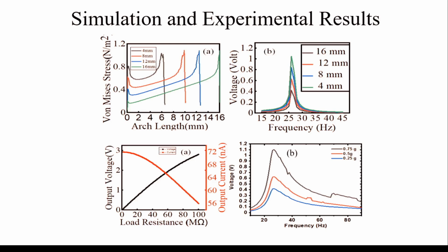But we can think that there could be a loss because of the mechanical structure. We have the electromechanical coupling coefficient, which will also give some loss. And during the coupling of kinetic energy to the mechanical structure, there will be loss. So we can understand. Further, we are trying to match and validate. Maybe we have to create a model which will include the losses, and then we can validate the experimental with the simulated results.